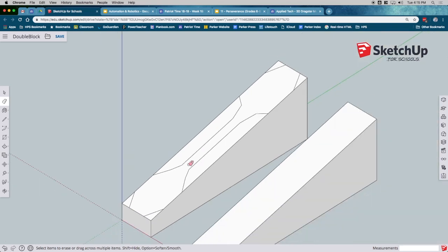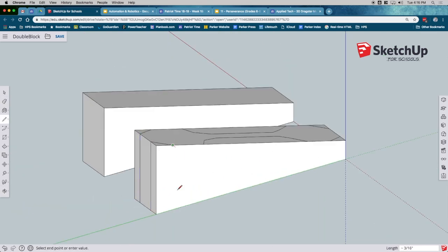Don't need that. Anywhere that my lines touch the outer part of the block, I'm going to put lines on the front and the side here, and that will make life easier. And we only need to do this, at this point we're doing this wherever we hit the outer edge. And you see how it snaps to the blue line? That means we're vertical to this line right here, and that's what we want to have. We want to be this blue line snap down,